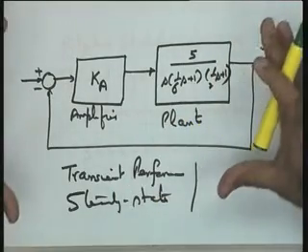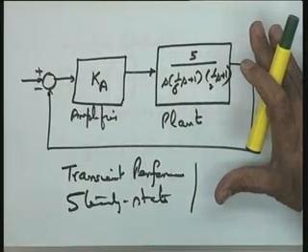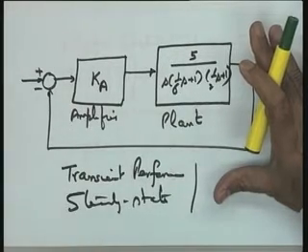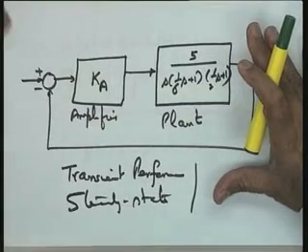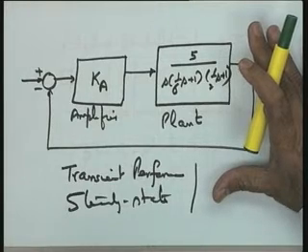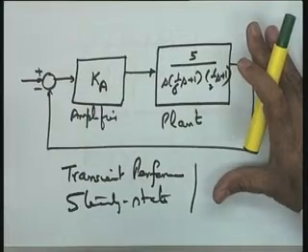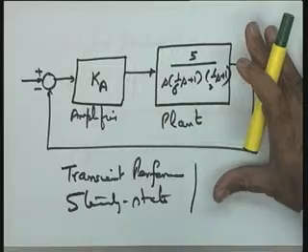It means I know that my system is not going to perform very well if the parabolic input comes up, and maybe the user says it is okay, his system is not going to receive parabolic inputs. And as far as position inputs are concerned, as far as constant inputs are concerned, it is guaranteed that for any gain the steady state error to constant inputs will be 0. So, no need of giving any specification.